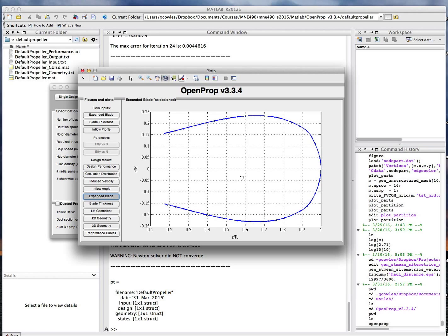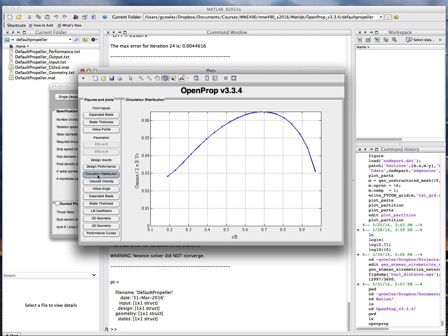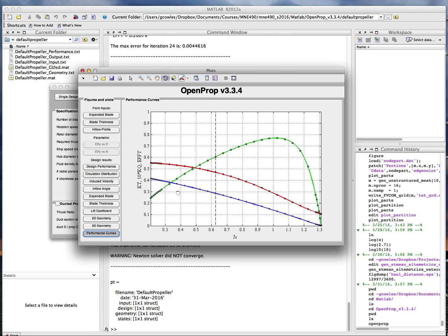For the propeller series we're looking at, they're 0.4, 0.6, 0.7, somewhere like there. The higher area ratio is about 0.7. I haven't looked at some of these other ones. You can have a look at these: induced velocity, circulation distribution, and link these back to our talk about lift. But I won't ask you to do that. So the key thing of this, and then we'll go to the performance curve.